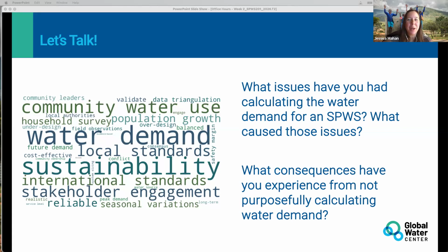So you do have to know the community a little bit and be familiar with maybe their actual water consumption to be able to gauge where you fall into that half to 3 times range. But there are a couple of reasons for the lower limit as well as the upper limit. For the lower limit, as you mentioned, solar only runs a few hours a day. Assuming it's our only power source, we only run it when the sun is up. But we typically need more water, especially late in the evenings or early in the mornings.